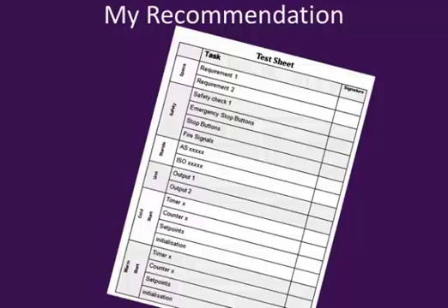Check it complies with standards. Check the outputs respond correctly to the inputs. Then check the timers, counters, and values such as set points are correct after events like cold starts and warm starts. That's it for testing.